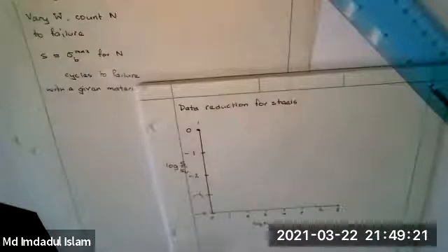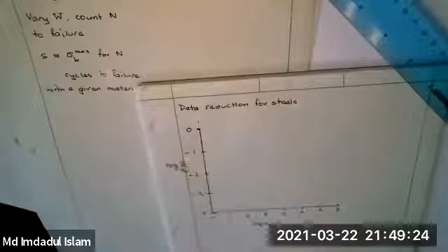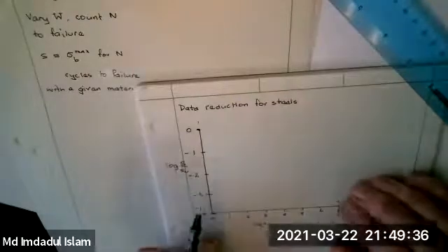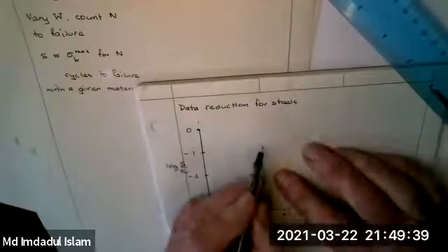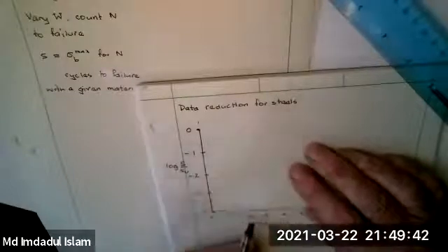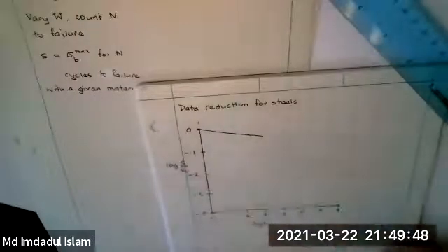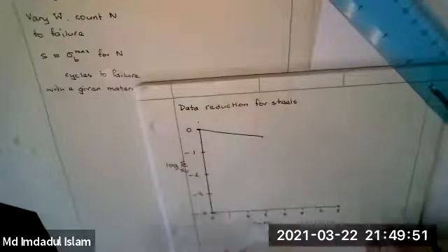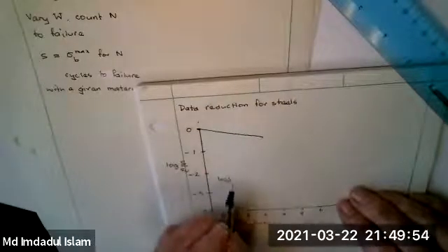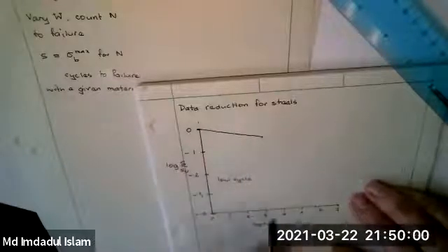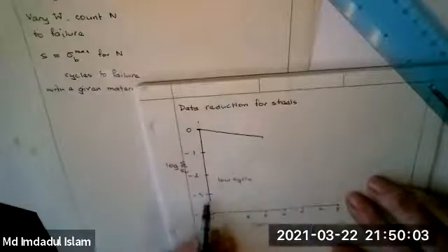And this is what the data looks like. The general trend you'd expect is down like this. Okay? As I tried to show you with the paper clips, during the low cycle, which is what the paper clips were, the stresses are rather compressed. They don't vary that much. And so it's actually kind of flat. Okay. That's the 10 to the 3. This is low cycle. When we get to 10 to the 6, we drop off more rapidly.